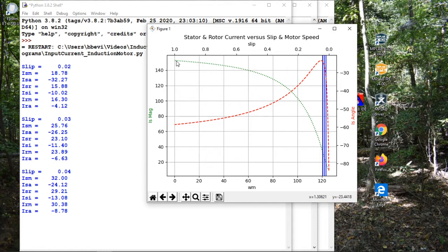So with an inductive impedance, voltage leads current, ELI the ICE man, right? And current leads voltage in a capacitive circuit. So anyway, that's a lot of current right there, okay? So that's what we've been told and we know. Now let's go in and let's expand this.